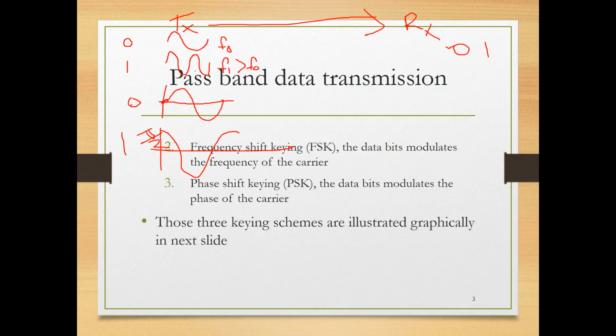So when the receiver checks the sinusoidal signal and sees that it starts from the origin, after it makes the synchronization and the estimation, then he knows that this is 0. But if it starts from pi over 2, this is 1. And by these rules that you establish, you can communicate your digital data bits using sinusoidal carriers. Simply like this. Now, what else? Think with me. What else can you bring?